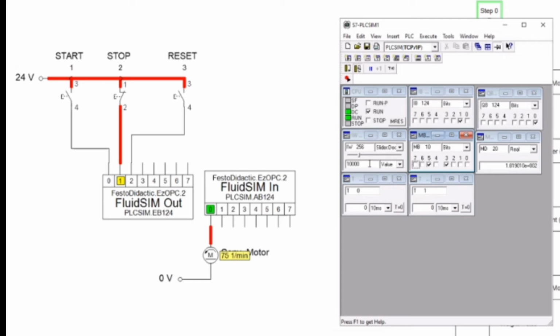And here we should return the value of the weight back to less than 5 pounds. So I'm going to move it all the way to the start. And as you can see, the timer for 2 seconds that indicates the pallet has already left the weight scale started and finished. And when this timer finished, we can start the sequence all over again.